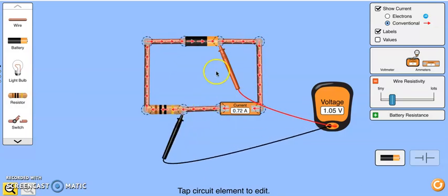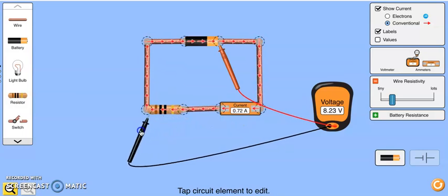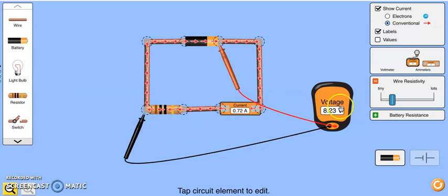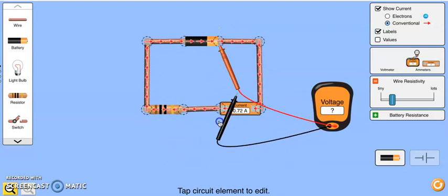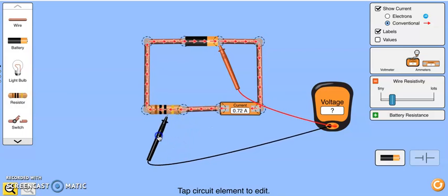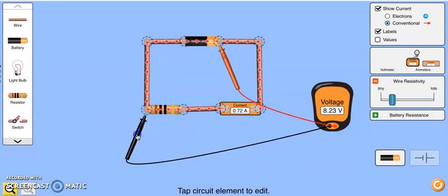All right, so what you're going to do is measure the voltage drop and the current. That's easy to do. And then you're going to do it again just simply by moving it here and measuring the voltage drop on the other side of the load. Okay, I'm not going to worry about moving it to a 3rd spot. And notice that the current doesn't change. The current doesn't depend on where I move the meter. The current is staying the same no matter where I put the meter. It shouldn't change. We wouldn't expect it to. The meter shouldn't affect what we're measuring.